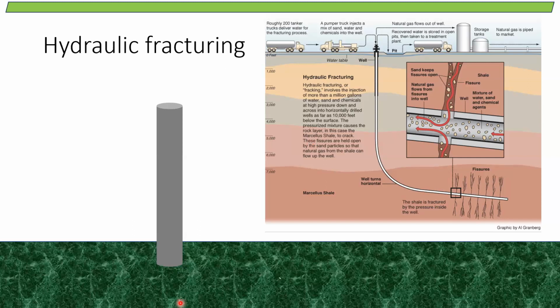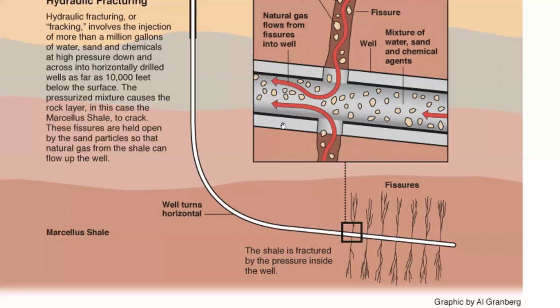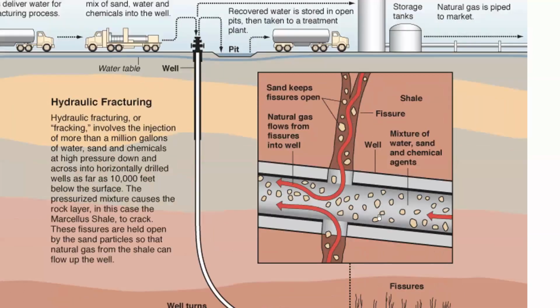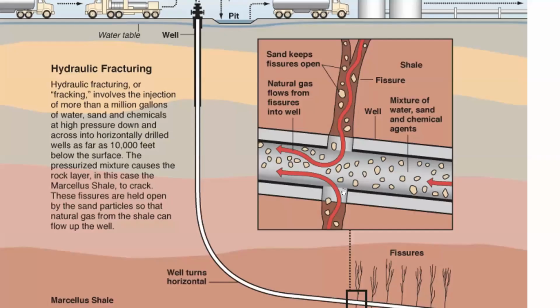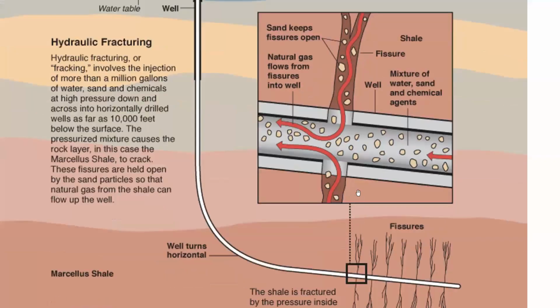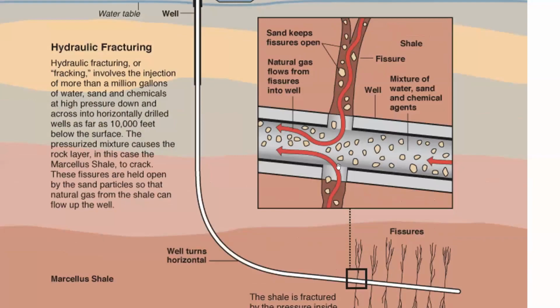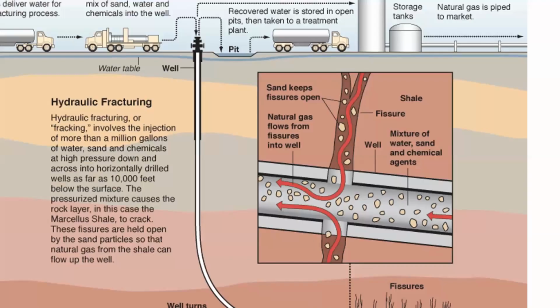So you can see over here, I will just zoom the diagram. You can see that hydraulic fluid, this is the wellbore, and it started to generate fractures into these perforations. So you can see this is the point where exactly they're zooming. You can see how the fractures and fissures have been generated over here. In this hydraulic fluid, it carries some sand particles as well as water. So it is a mixture of some part of sand, water, and other chemicals, so that this sand particle acts like some kind of barrier to hold the fracture.